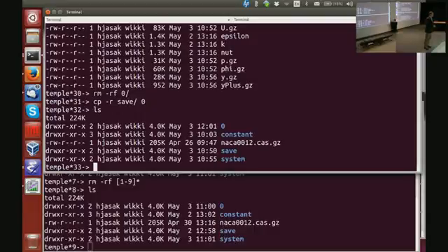For the people who are advanced, among the tutorials there is one called engine cooling. What I need you to do is to convert the Star-CD mesh and run the simulation. When you're finished, create a scalarTransportFoam case and run a transient simulation tracking the scalar from the inlet to the outlet to find out how the domain is filling. If you're really advanced, then show me how to calculate the residence time as well. That will keep you amused for a couple of hours, and in the end we will do it quickly.